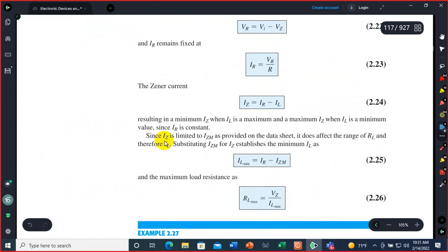So IZ is limited to IZM, the maximum zener current, as provided on the data sheet. It does not affect the range of RL and therefore IL. Substituting IZM for IZ establishes the minimum IL as...